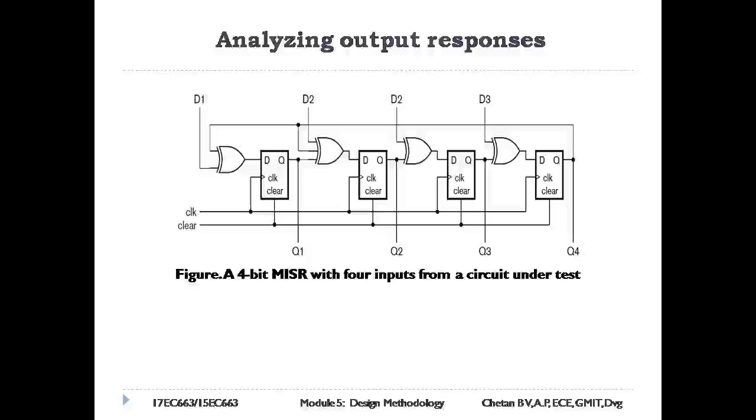This technique is closely related to the use of LFSRs for test pattern generation, and the same mathematical theory underlies the operation of both. A signature register forms a summary, called a signature, of a sequence of output responses. Two sequences that differ slightly are likely to have different signatures.